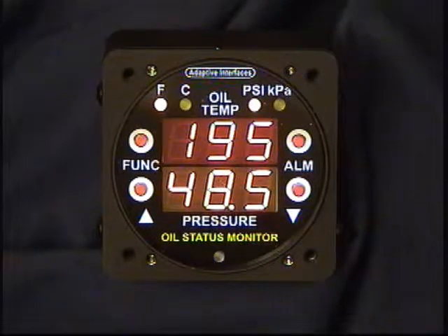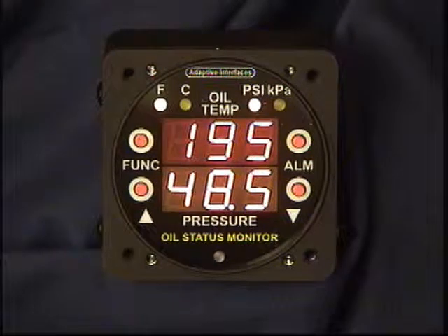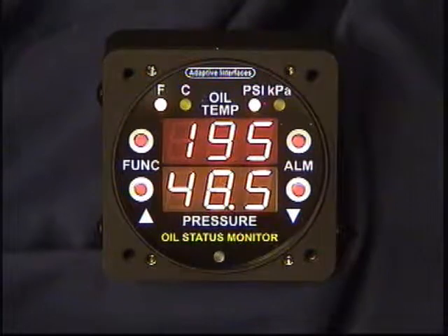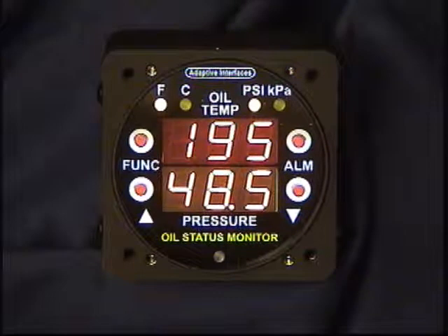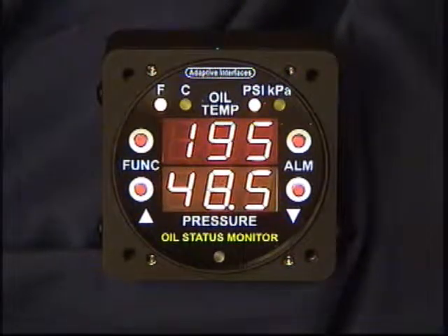Another function that the instrument has is an internal backlight, and that can be adjusted with an external control voltage, normally done with a potentiometer or control on the instrument panel. To demonstrate that, we can turn the display backlight almost completely off, and we can lighten it up as well, for different flying conditions and lighting conditions. You can set it to whatever you need. We'll set it back at an optimum level right here.